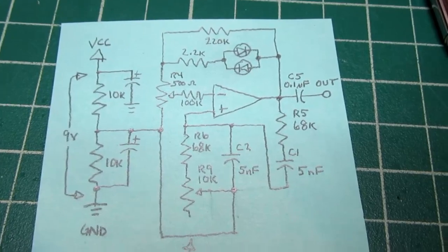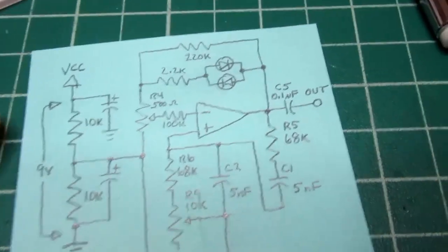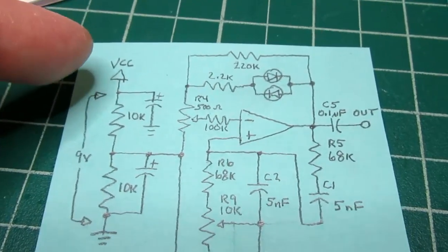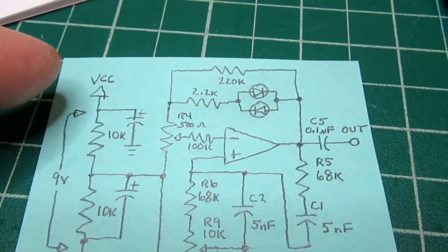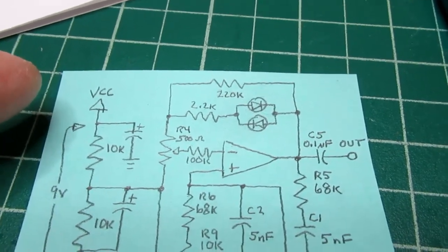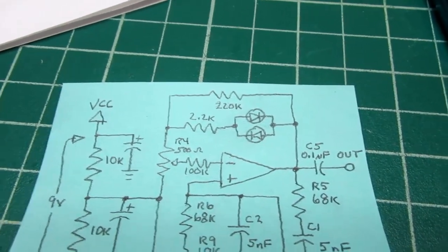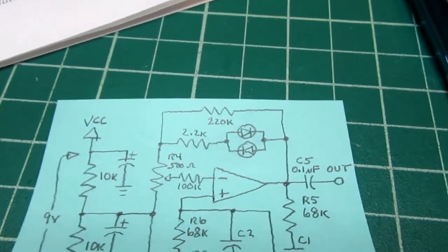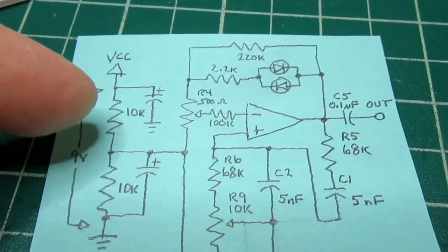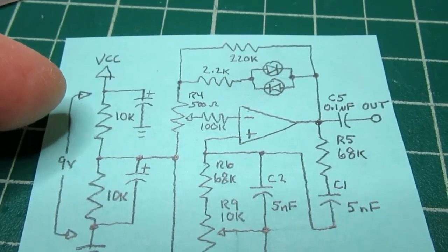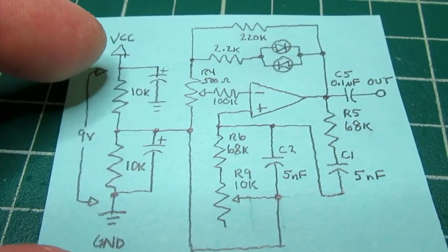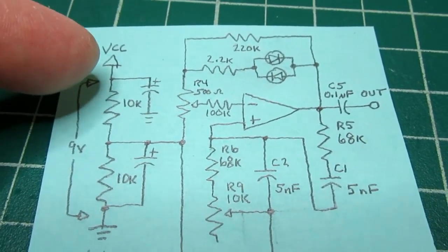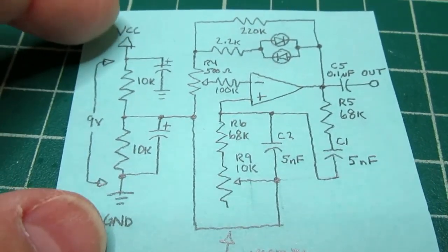So here's how the Wien bridge oscillator is laid out in this kit. Because it's a bipolar output, in other words, it's an alternating polarity signal, or true AC, as opposed to a modulating DC signal. It does go above and below ground or circuit common, but it uses a single pole or monopolar supply, which is called VCC and ground.